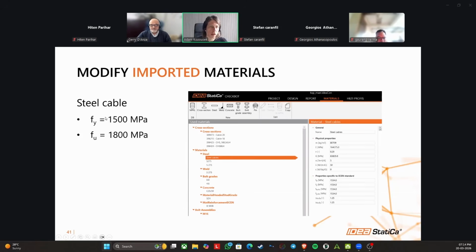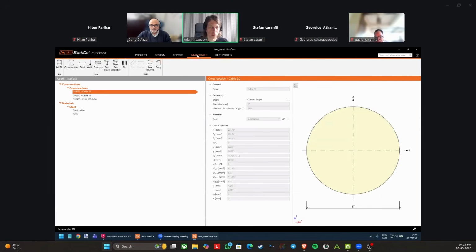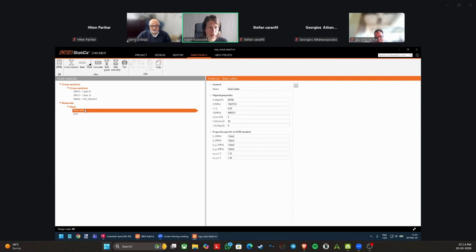I want to have these values of the strength of the steel for the cable, the yield and ultimate. So let me show you how to do that. Go here to materials, click steel cables, and here I simply rewrite 1800, and I will edit this to 1500, right?